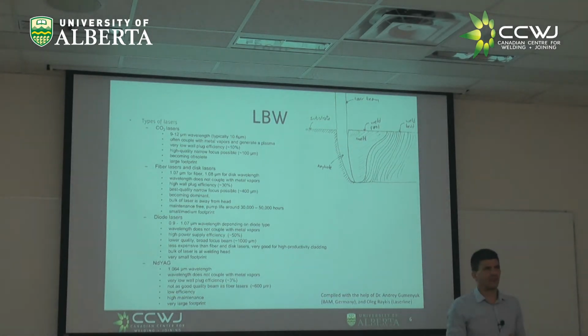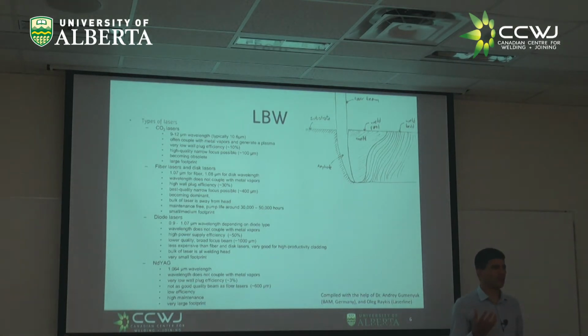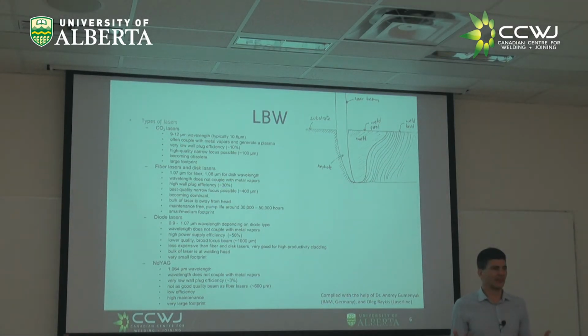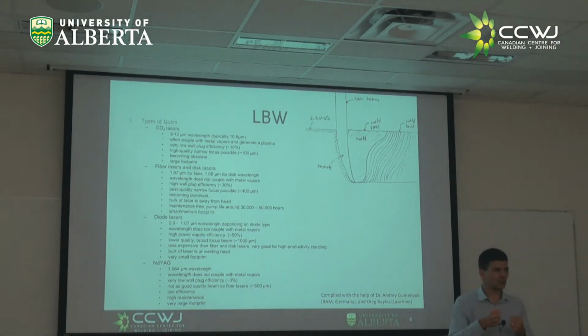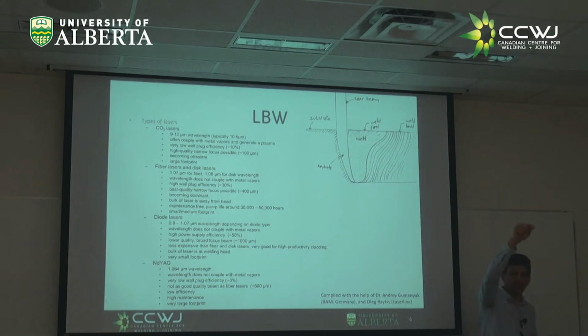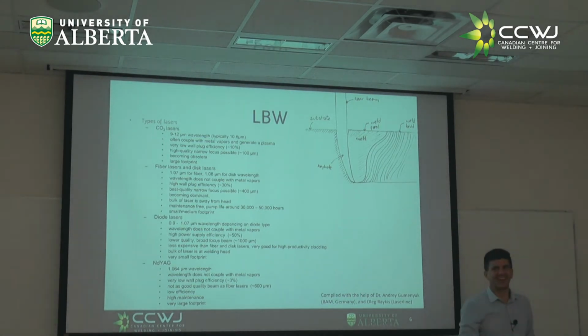Now, for example, this is a real case of a company here in Alberta. They mounted the machine over a seam on the floor. So when you have the freeze and thaw during the change of season here in Alberta, the floor moves, right? Haven't you seen that in your houses? Often some doors open differently in summer than in winter. Well, now try to aim like 10 kilowatts of laser going through a bunch of gold mirrors, right? Very difficult. They are a pain.